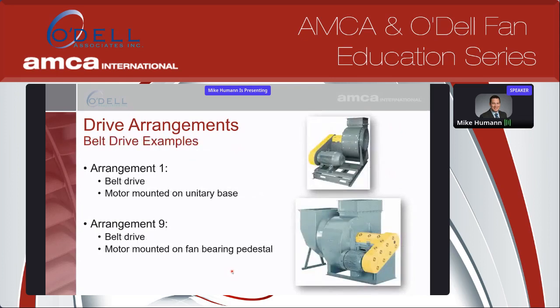So now we'll talk to the other side. We'll talk about the belt drives. You see here we have an arrangement 1 in the upper right-hand corner, and we have an arrangement 9 fan. The difference is that in arrangement 1 you have a unitary base or floor mount motor, and in arrangement 9 the motor is actually mounted on the side of the bearing pedestal. Obviously there's a footprint impact between the two.